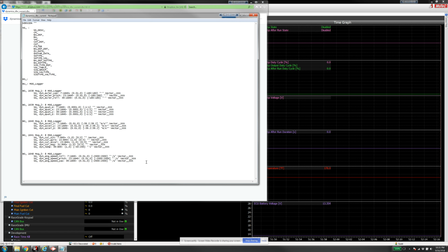And this is what a DBC file looks like. If you're not familiar, this is basically just a text file at its bare core that has a bunch of symbols and words that indicate what information is being transmitted by the sensor and some information about each message. As a quick explanation, this is the decimal representation of the address. These are 3 different values that are transmitted on this address, and all 3 of them are 16 bits long. These are the offsets of the message.